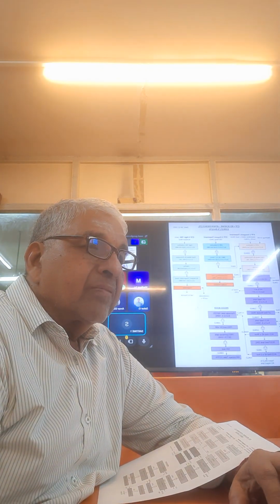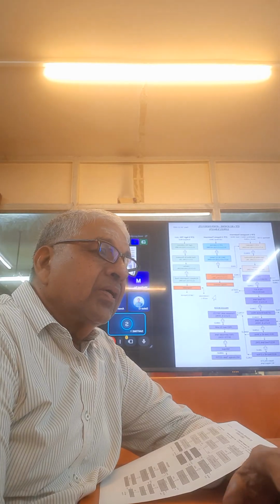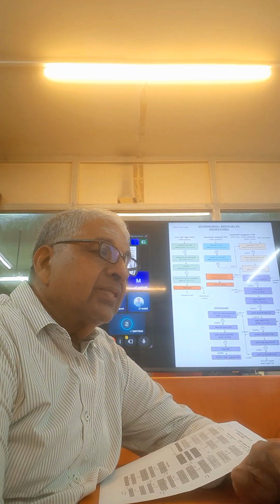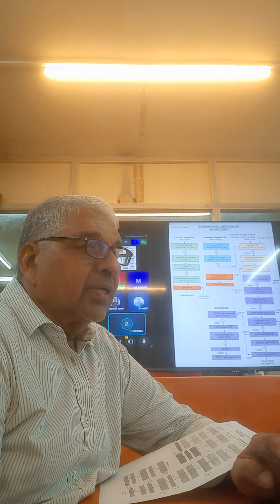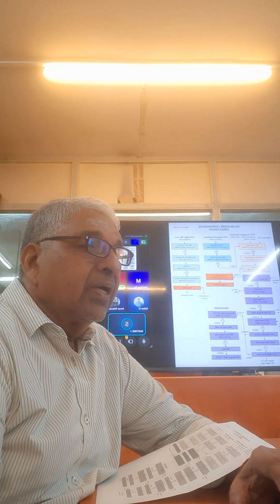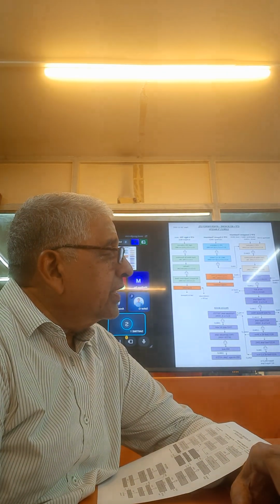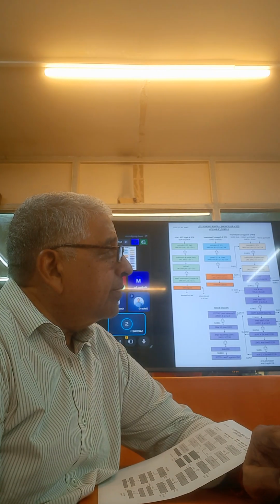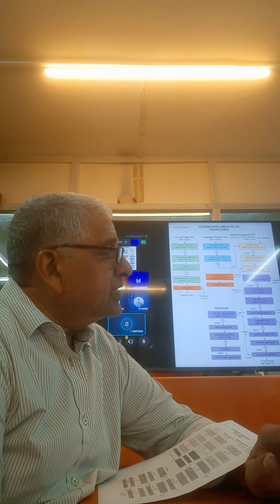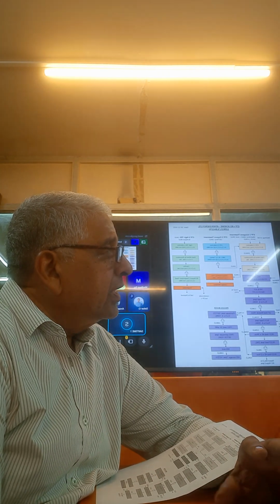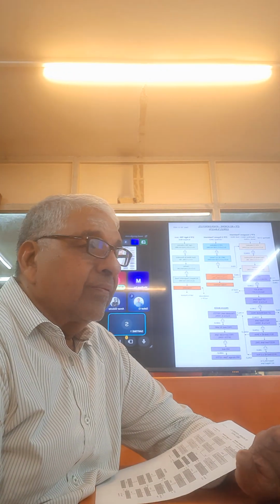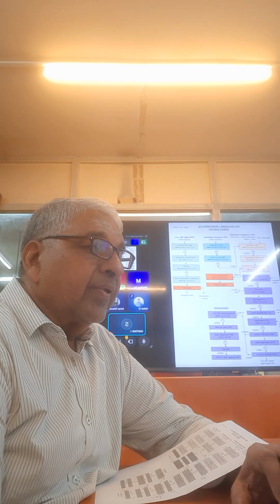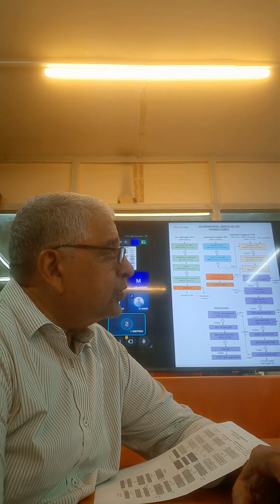See, in all these cases, you will have some floor washing. If you do washing around the decanter, thickener, anywhere, some spillages happen, then they will be collected in one sump and that will be pumped to the ETP1 collection tank. So the filtrate from the decanter can be taken to that sump also, which will be nearby.